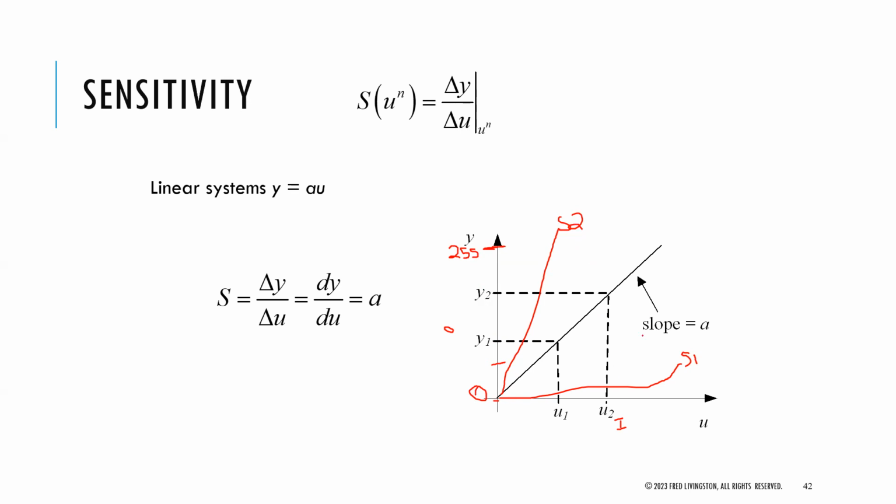In this case, sensor 2 may be a better fit. It's going to use up my full range in my analog to digital converter for a given input. If my input is in this range here, you can see anything past here, I will not be able to actually measure. So I would like to say, given an input of X units here, let's say this is my sweet spot, what is the better sensor for that? Sensor 1 or sensor 2? Does that answer your question? Yeah. And in this case, sensor 1 is probably, I drew it outside of the range of sensor 2 there.